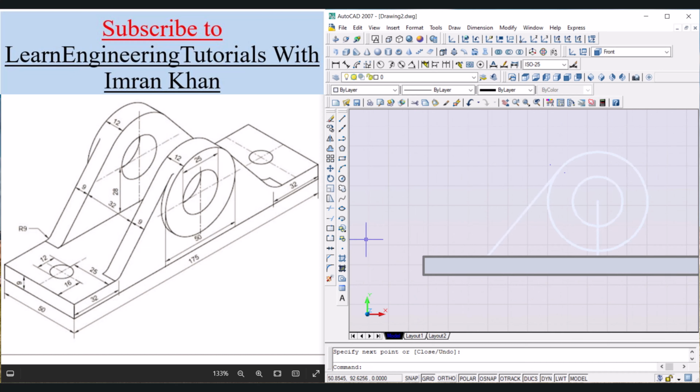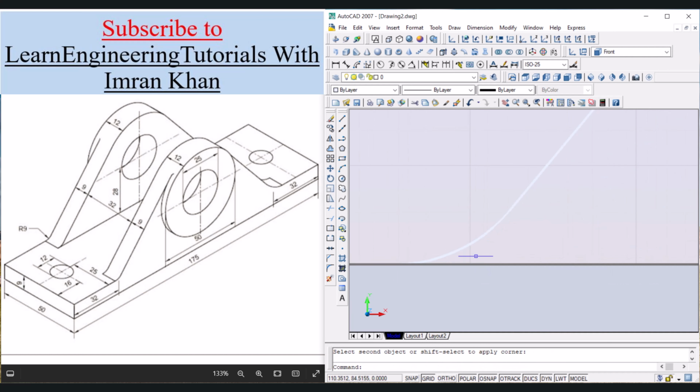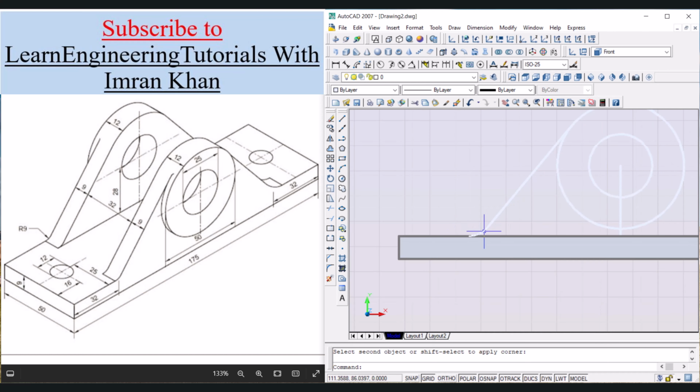Now we have to fillet this edge. For that click on fillet icon, radius is 0 so R, enter, and here the radius is given as 9, so 9, enter. Click on this line and click on this line. Now we can see that this edge has been rounded or filleted.